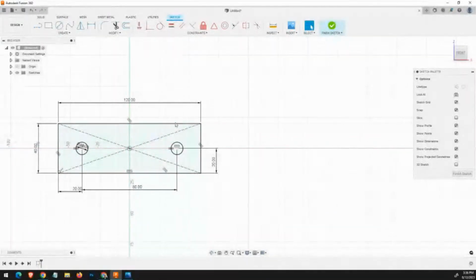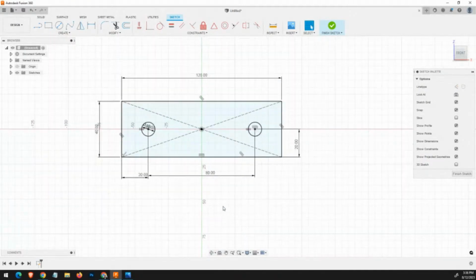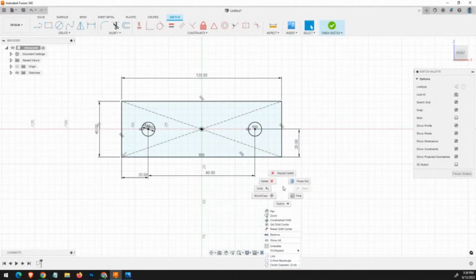Let's now proceed. So going back here to our 2D drawing of the plate, if it's done and fully defined, we can click the green button on the side. That is Finish Sketch. Okay? Or, how do we do the finish sketch here?